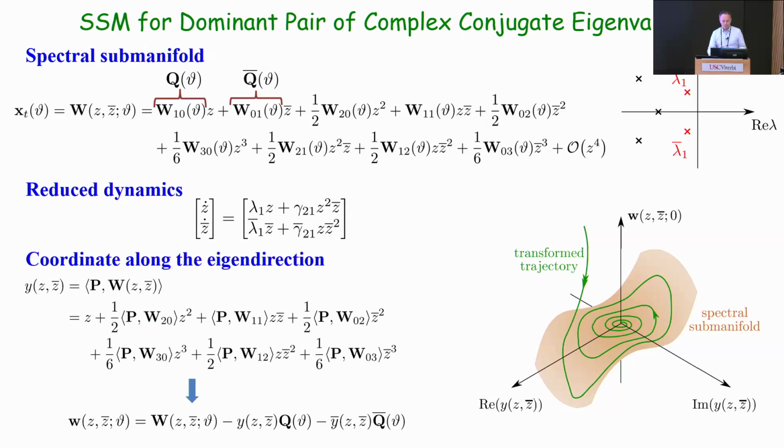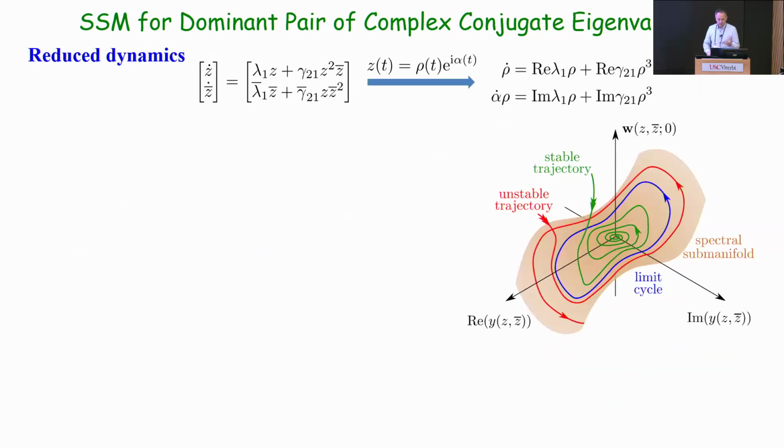However, there is the possibility that we now can have an unstable limit cycle living on this surface, and that indeed changes the problem. And this is what we have seen in the case of the traffic jams, that indeed there was an unstable limit cycle. So now it's important what happens on this manifold, right? It's not just that I go to the manifold and then on the manifold I go to my equilibrium, but indeed, depending on the initial conditions, I can see either a decaying solution or something which eventually grows into a congestion wave.